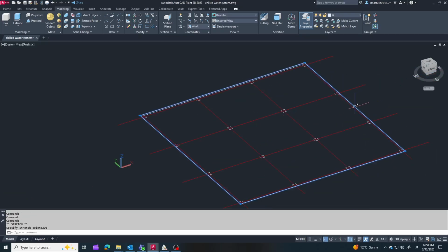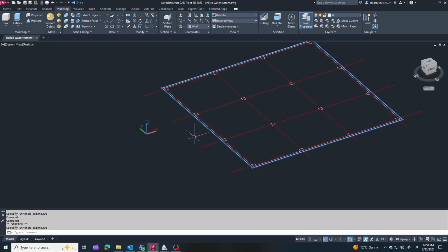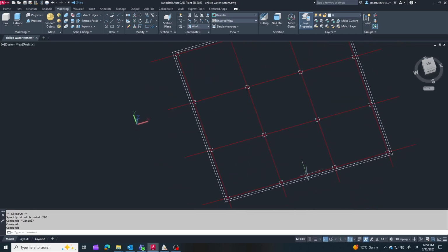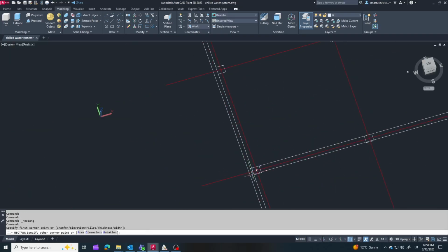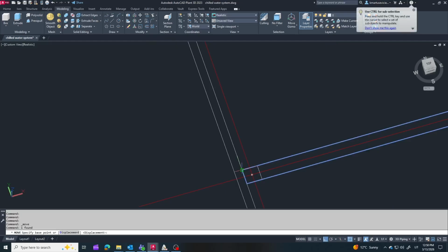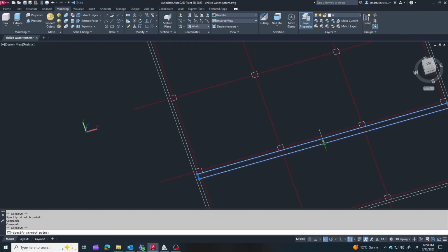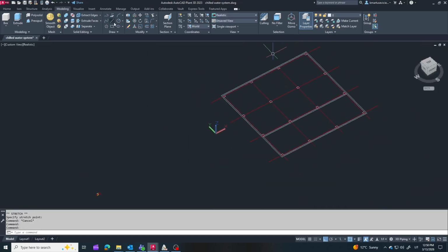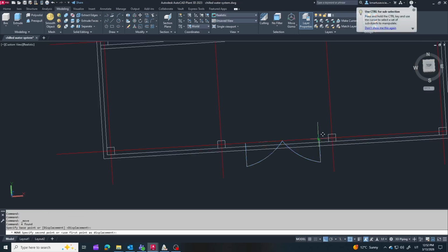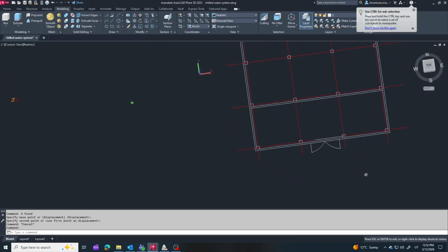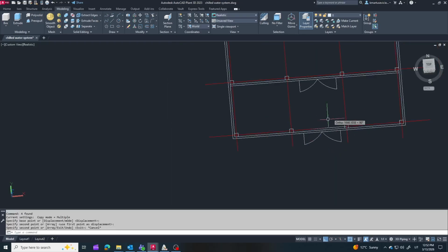Along the perimeter, I add 200 millimeter thick walls, plus one internal wall to divide the space. For the internal wall, the exact position often depends on the wall type. If the wall is made from sandwich panels, it is usually placed next to the columns because structural beams typically run between the columns and the panels can be fixed directly to the frame. Sometimes the wall can also be installed between the columns, depending on the building structure and the layout requirements.